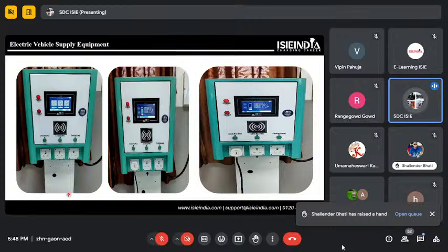So you can see that this is one of the charging infrastructures for level 1 and level 2 chargers, and it has a rating of 9.9 kilowatt. It has three sockets, and each of these is a 16 ampere socket. It can be accessed by manual RFID card or through the app via the server also, right?